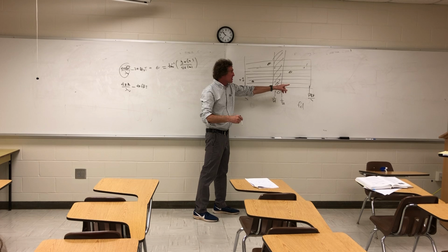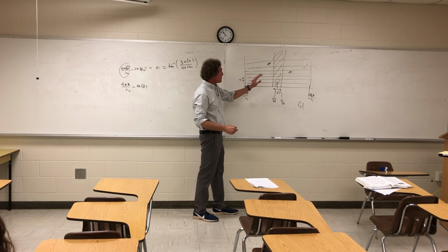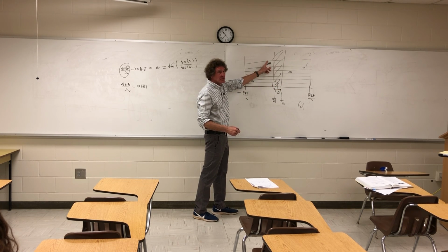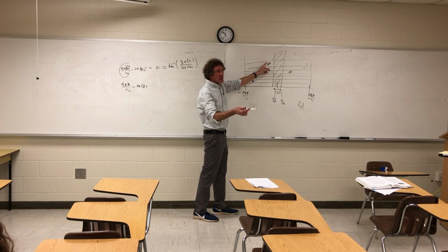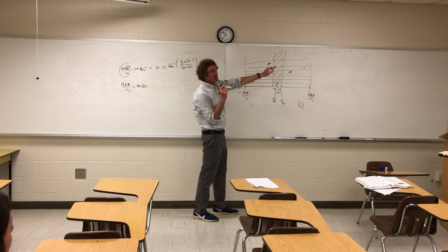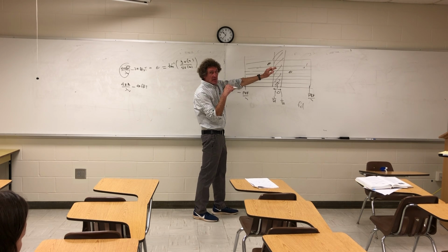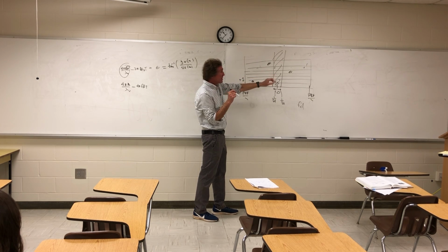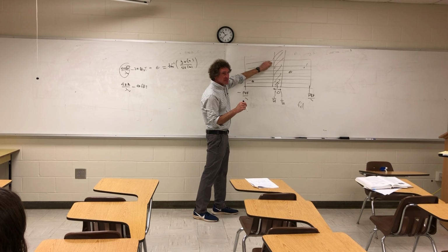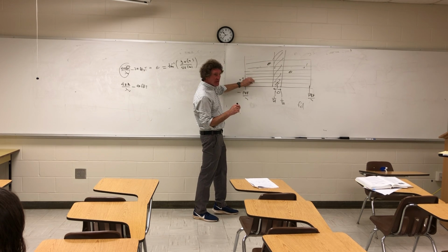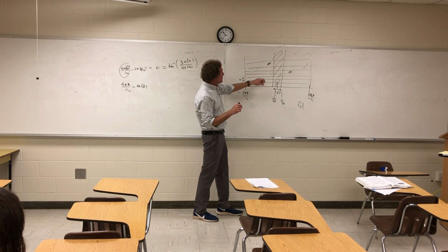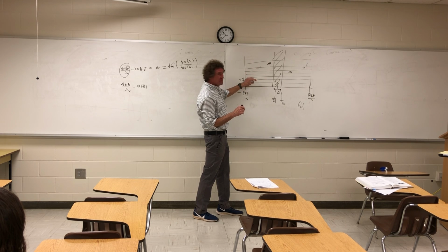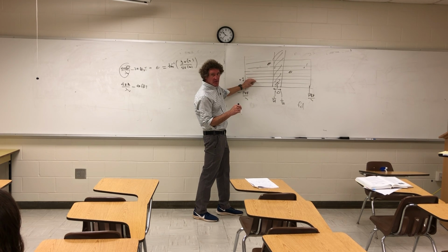Now the next pulse that goes out, we're going to see targets. We may or may not see these. If we see the same target, we're getting a more confident look at it. We send it out again. Remember, we're going to keep on the azimuth and elevation at that target in that area for a total of a dwell, right? We're going to keep sending it out. So over the course of a dwell, if you have many targets there, but maybe not many here, it doesn't show up in everything, then you're very confident about that, but you're not confident about this. Y'all follow me on this?